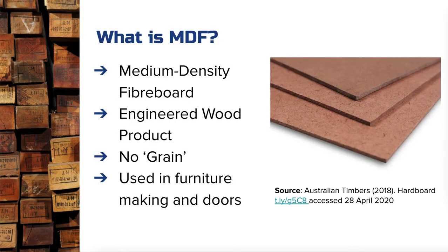Now, MDF is a fiberboard. There is MDF, medium density fiberboard. That's the one we need to know about here. But there's also another one called HDF, or hardboard, high density fiberboard, sorry. Essentially the same thing. It's just all about the size of the fibers that are used within the material. So you can see I've got an image there of hardboard. I've put the hardboard there because it's a little bit easier to see. When we look at MDF, it tends to just look like cardboard. It's not as easy to see the little fibers in there, but you can see the fibers here.